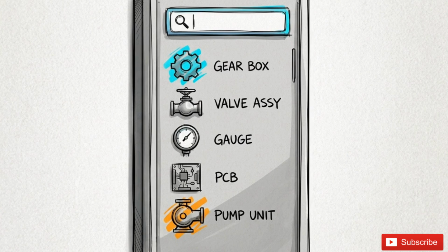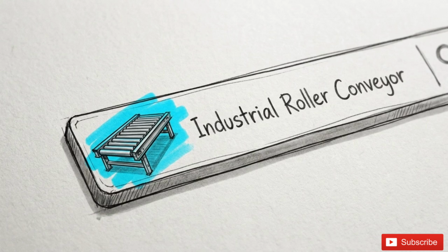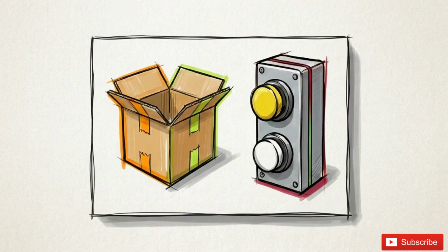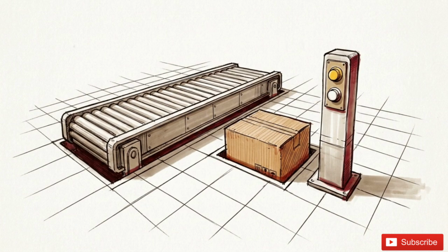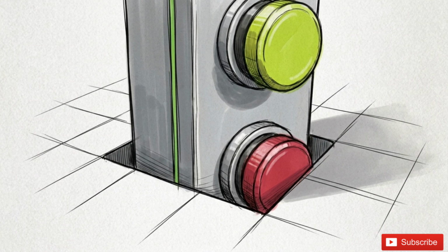Now let's bring in our hardware. Open the component list on the right. Search for a 2-meter belt conveyor, a box, and a button station, and drag them into your workspace. You will notice right away that everything drops completely flat on the floor. The button station is practically underground, which obviously isn't where a human operator would stand.